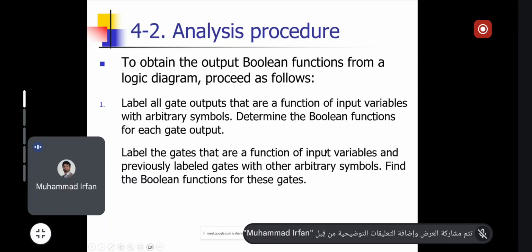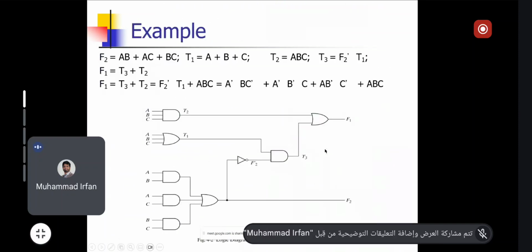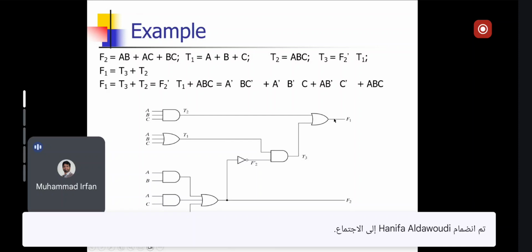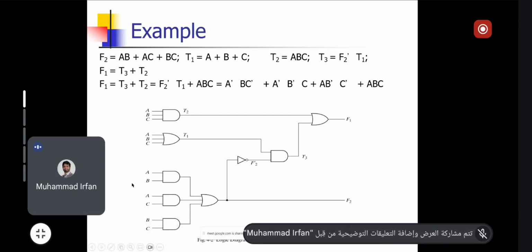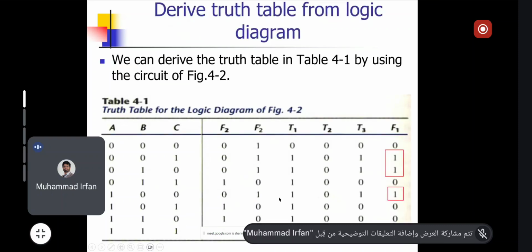Actually, sorry, that one is the data flow modeling. When we have Boolean expressions, when we have simply the hardware modeling, that's the structural modeling. So when you convert this into textual VHDL code, that will be the structural model. And if we have a truth table for that, that will be the behavioral model, like this one.